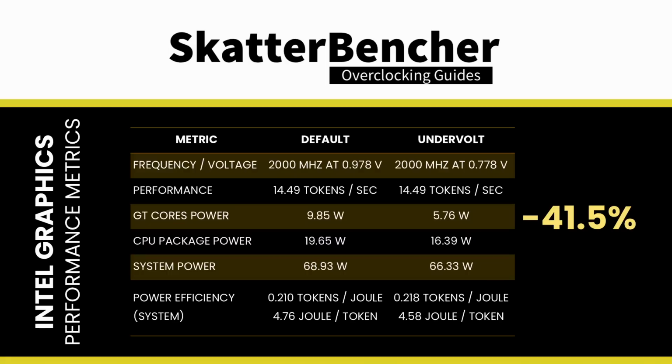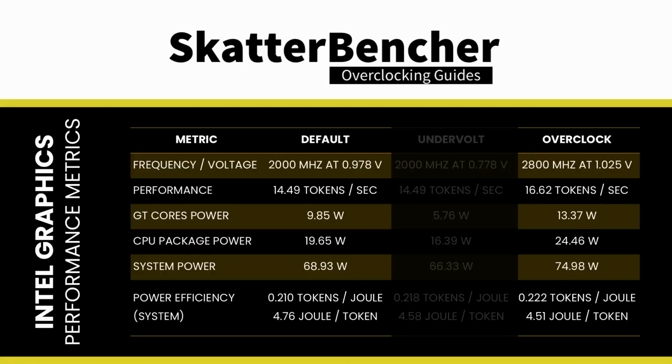On a system level, the power consumption reduction is not as much, as it's only reduced by 2.6 watt to 66.33 watts, a 3.8% reduction. That translates into 0.218 tokens per joule or 4.58 joule per token. After overclocking the Intel graphics by 40% to 2800 MHz, it generates 16.62 tokens per second. That's a 14.7% performance improvement.